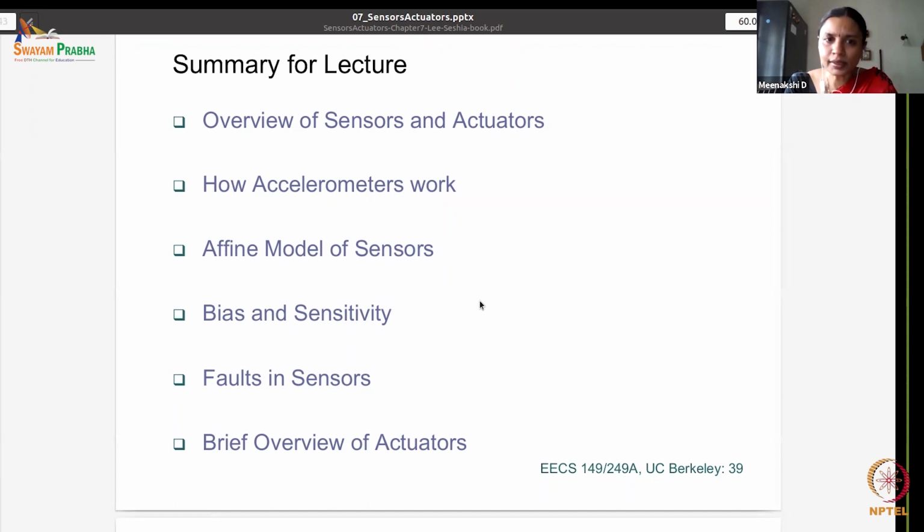So we write the interrupt service routine, which is a piece of code that we write to handle the interrupt. We register the interrupt service routine. And when the interrupt comes, which is given by this arrow, what happens? The processor executes the interrupt service routine by doing a context switch. When it finishes executing the interrupt service routine, it resumes doing whatever normal code it was doing.